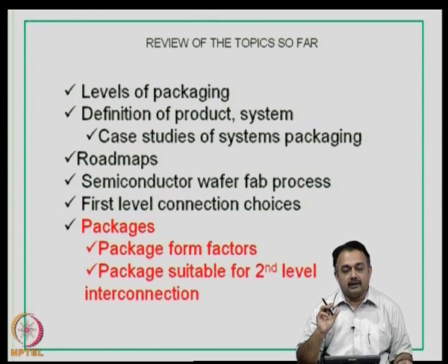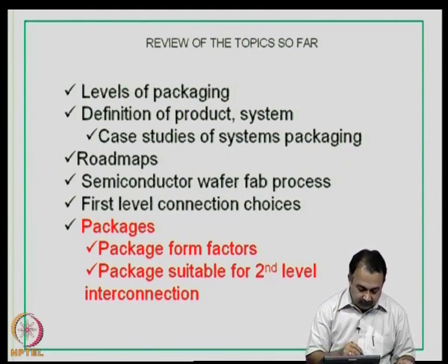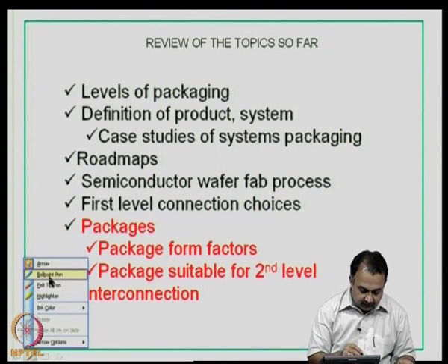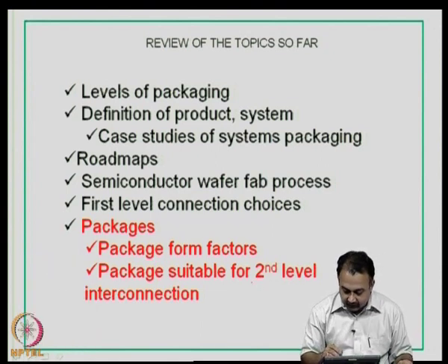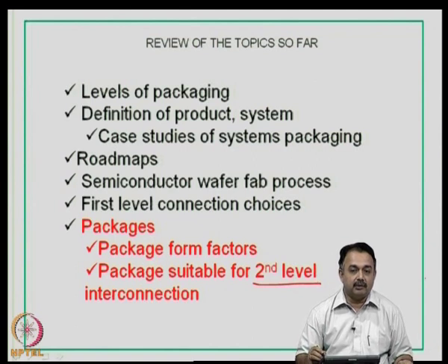We look at the suitability of packages for second level interconnection. I hope by now you are aware of what a second level interconnection is. The second level interconnection means your package is now connected to a printed wiring board. The printed wiring board is a system level printed wiring board, because a printed wiring board by itself can perform system functions.